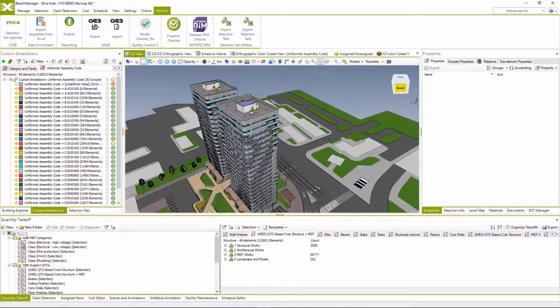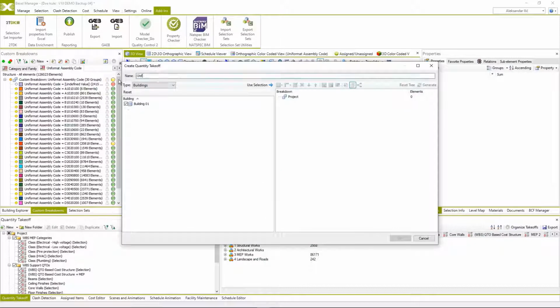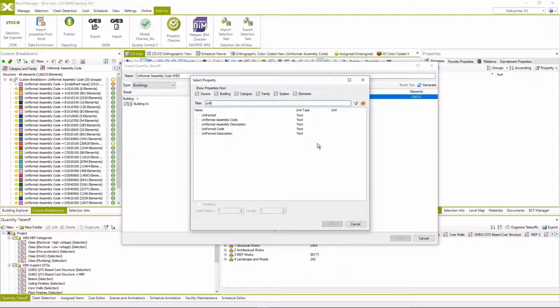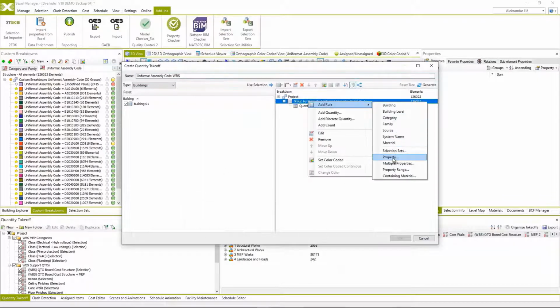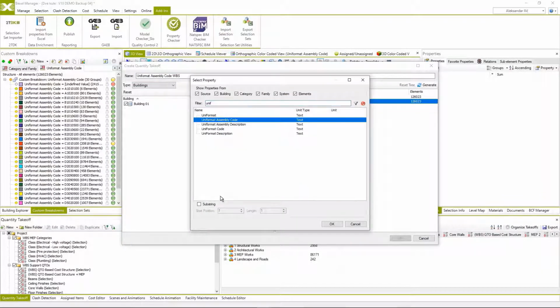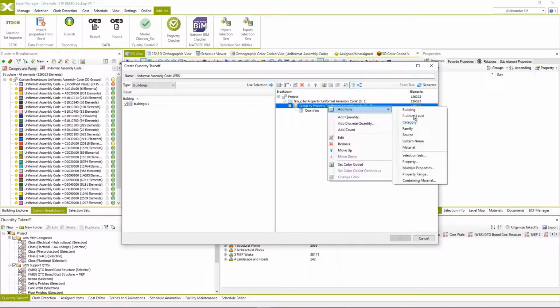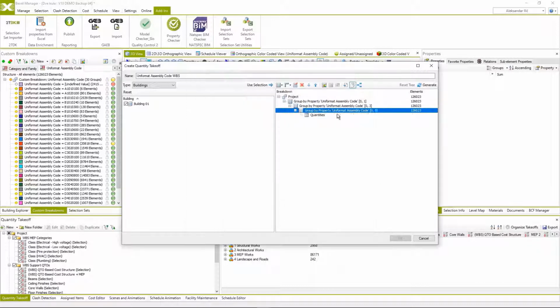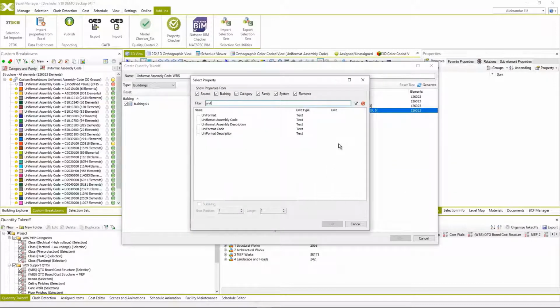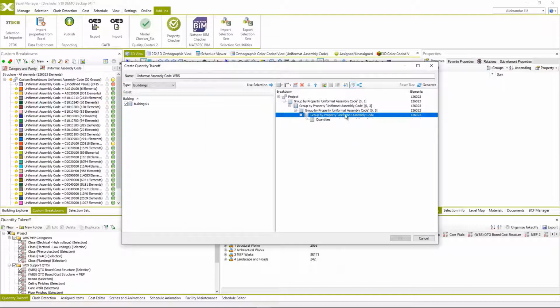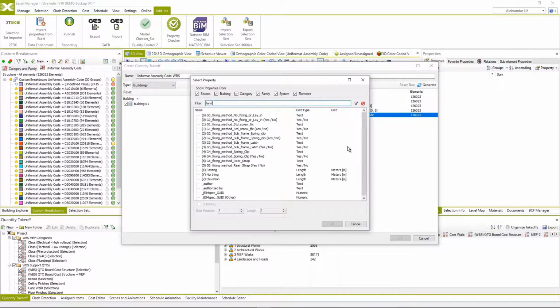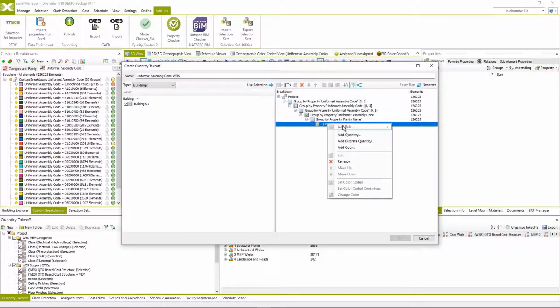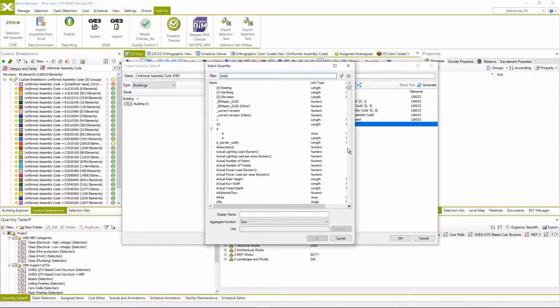So we're going to use the same model that we just enriched with the new cost classification codes, and based on these codes we're going to be able to develop a QTO, which will serve as the work breakdown structure for our cost classification. Using the substring command, we can utilize the Uniformat assembly code, in this case, that was populated with the enrichment add-in, and we can build the hierarchy, the structure of our groups of works, the structure of our future cost classification.